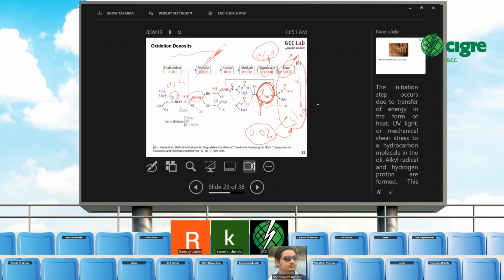Actually, we did inspection of some of the cable boxes. In fact, we also replaced the insulation supports available inside the cable boxes. And after replacement, other than the insulation support replacement, no visual abnormalities were observed. And after re-energizing the transformer, the trend of some of the transformers' cable boxes is still high. So that is the question. So we have kept them under observation.